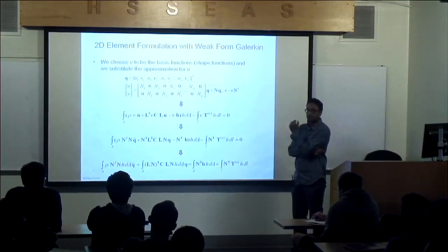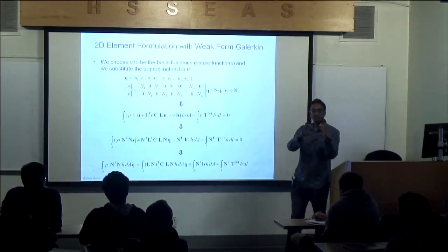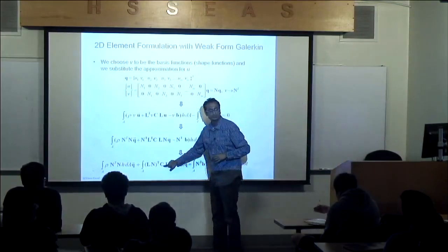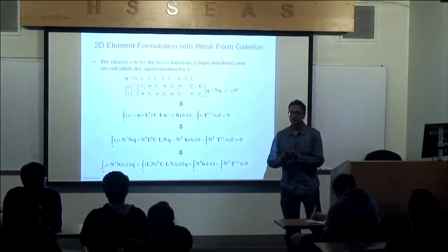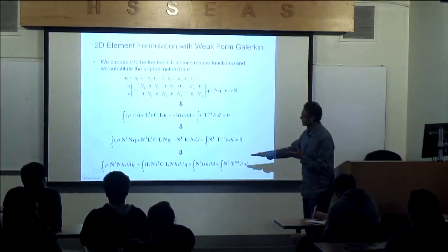I actually don't see any difference between the 3D plane strain and plane stress. The only difference is the constitutive law changes. This C changes for plane stress versus plane strain. That's the only difference in the two formulations, right? You guys have any questions on that?